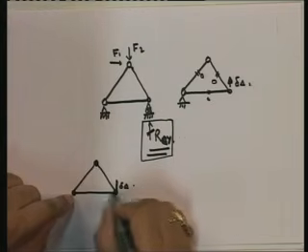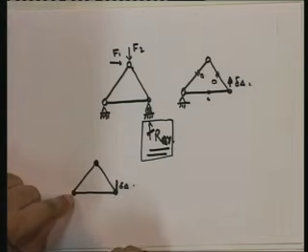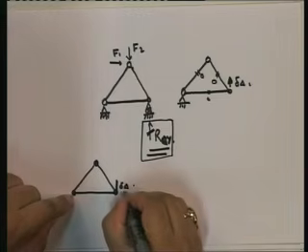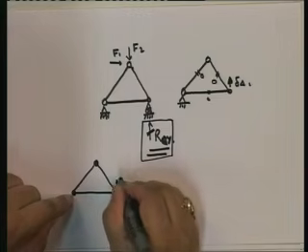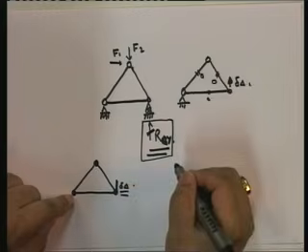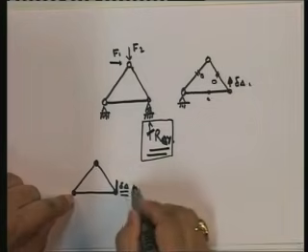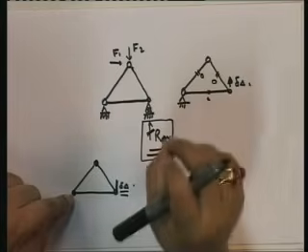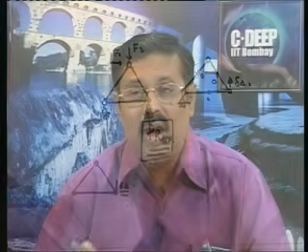In other words, you cannot have deformations in any of the members. Remember that the displacement that I give, although I'm showing it to be very large, is actually very small. Okay, so small displacements still hold true. The virtual displacement that I give has to be a small displacement. I might show it as very large, but I'm just essentially exploding it to show you. It's not as if it's going to be moving in that direction.